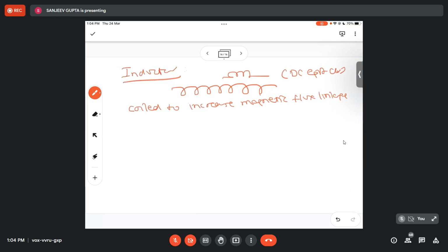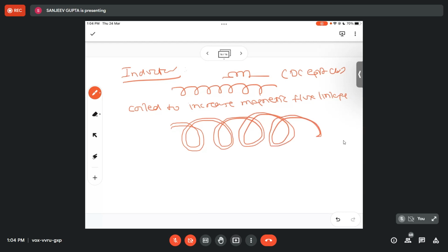Now, basically, my inductor, if I look properly, will look like this. It is a wire of a certain diameter. Can you imagine, something like this. So basically, this represents my inductor. Now you find there is a gap between the two coils or two turns, so it will also give rise to a capacitance. And because these capacitances are distributed, we name it CD. So CD becomes my distributed capacitance.